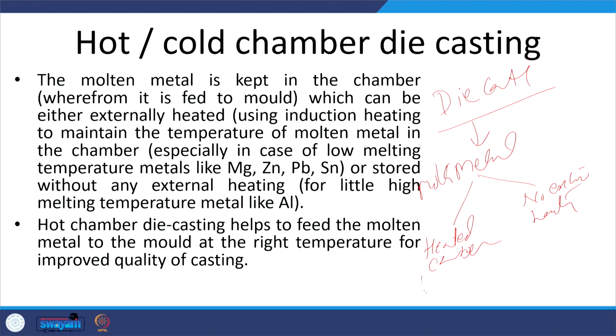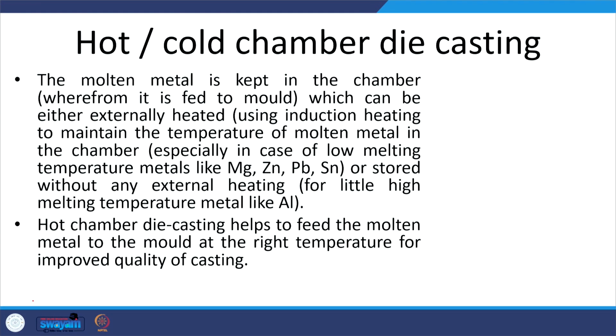When there is external heating using either resistance heating or induction heating, it is known as hot chamber die casting. Otherwise, it is known as cold chamber die casting when there is no external heating. Hot chamber die casting is preferably used for low melting point metals like zinc, magnesium, etc.